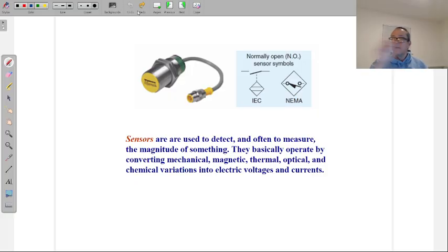Whereas with a sensor, I can send 100 boxes per second in front of that sensor, and it will count every one of them. So there's where the biggest advantage has changed the game a little bit. This is why the computer PLC was needed, because you can't do this without a computer. You can't have that sensor trying to activate relays 100 times per second. It's just not going to physically do it. It'll burn this out.